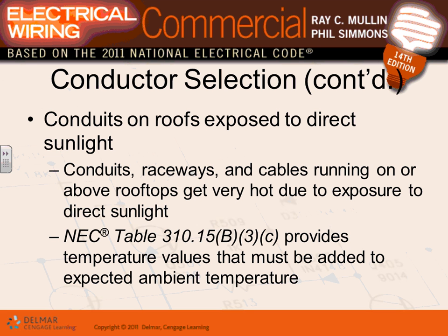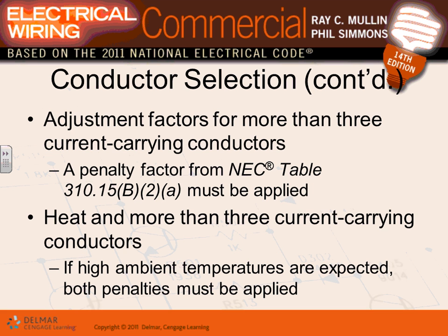Cool? The table that deals with this one, 310.15(B)(3)(c), gives values to add to the temperature if you are to put a conduit on a roof. And I will go through a couple of calculation examples, guys, with you, just a refresher. Just be aware of that one. We'll go through a couple of examples.